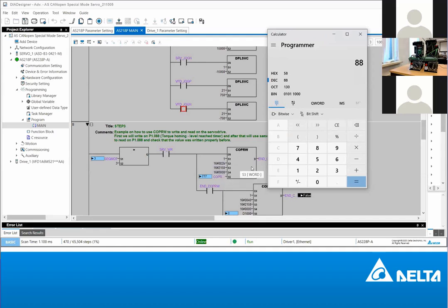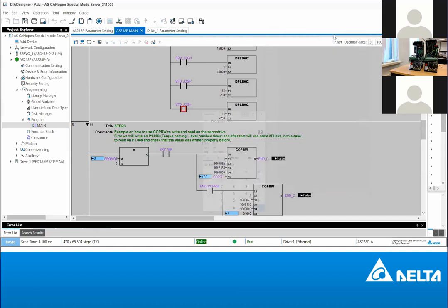Then you write the parameter register. So now what are we going to do here? I want to write this 77 to parameter 1088 in the drive. So let's see, why is this 77? You may ask. When we initialized this project, we wrote 77 at the beginning. This is network 8.